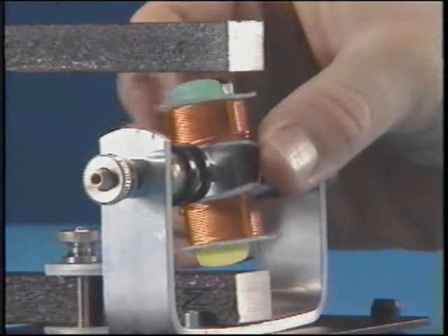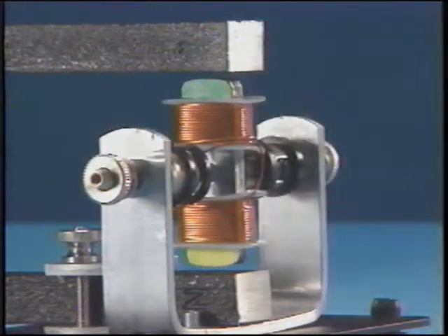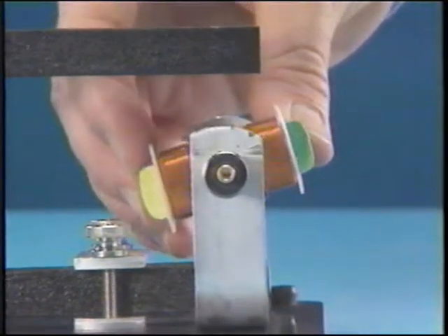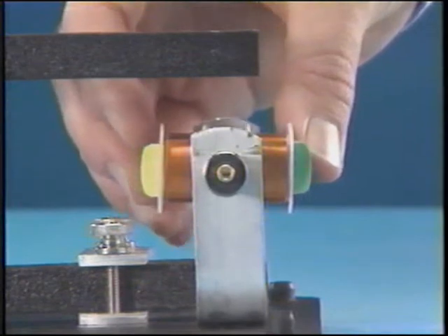As the coil rotates further into a vertical position, it once again cuts an increasing amount of flux lines until it reaches a point where the maximum amount of voltage is being induced. Finally, the coil rotates back to the original position where the coil is situated parallel to the flux lines, and no voltage is induced. This simple procedure demonstrates the fundamental principle of all AC generators.